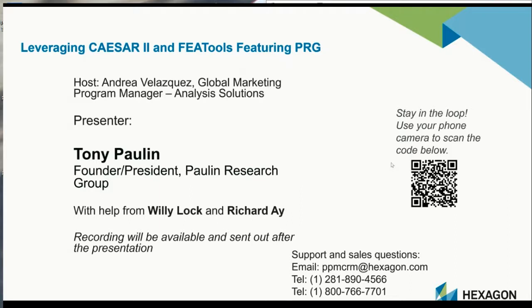Okay, perfect. Do you offer analysis options for support locations not on shoes, particularly when point loading, say, round bars involved? Yes, there's a cumulative damage tool that provides a variety of ancillary calculations for pipe. So if a person has a Caesar model with a support at a given location, you can pull up the cumulative damage tool, go into local loadings, and tell it that you've got a bar support. Interestingly, that was developed for bar supports with corrosion, because a lot of bar supports develop corrosion under the bar. So you can check the bar support as new, and you can also check the bar support with various sizes of corrosion between the bar and the pipe.